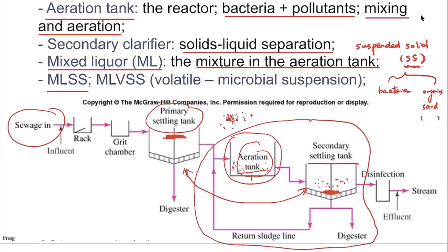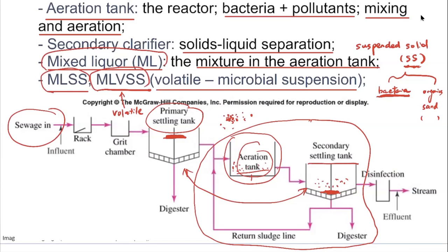So further, we define this bacteria section, or the microbial section, as the mixed liquor volatile suspended solids. Okay, so basically the MLVSS specifically defines the microbial suspension in this mixed liquor. There are quite many definitions here. We're going to use them in some calculations.